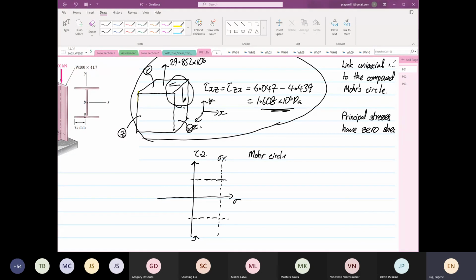I will elaborate on this more. So this is one value, this is point X, and point Y is tensile. Again, this is not to scale, and it's rotating anti-clockwise. So this is our point Y. Then from here, I'm going to sketch out a circle. It's not perfect. This is our Mohr circle, our 2D Mohr circle. And if we go into 3D, which we'll do next week, we have another point down here, which is our Z.